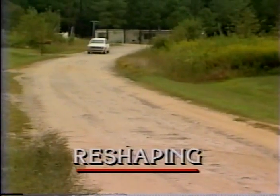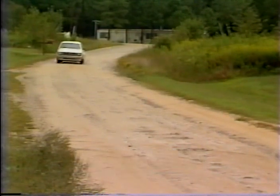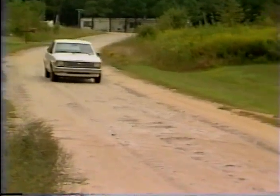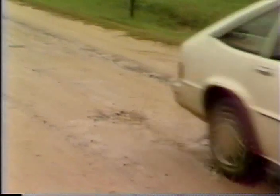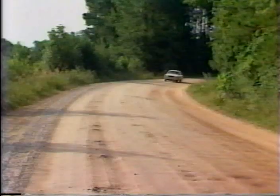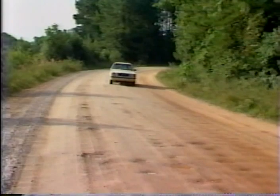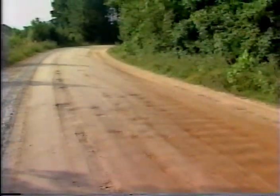The other maintenance operation is reshaping of gravel roads. Eventually, due to a combination of weather and traffic, the crust of the roadway may be broken down, creating a rough riding surface. The surface may have potholes, washboarding, and rutting. A roadway in this condition must be reshaped and requires cutting through the crust of the roadway to create a new smooth surface.